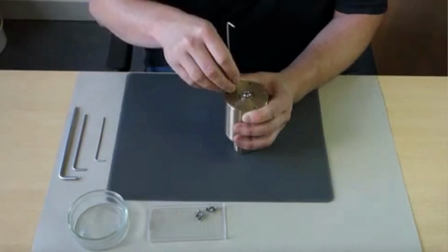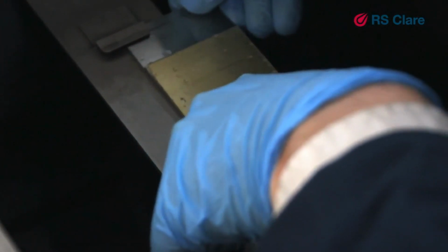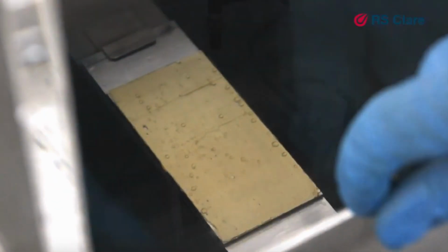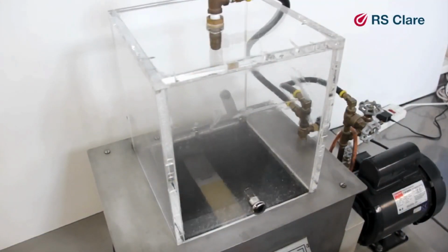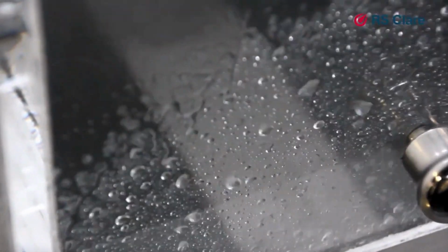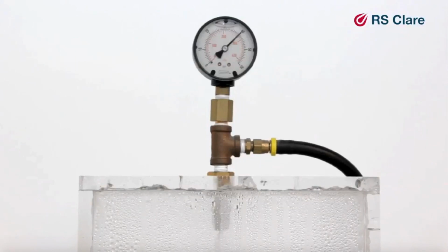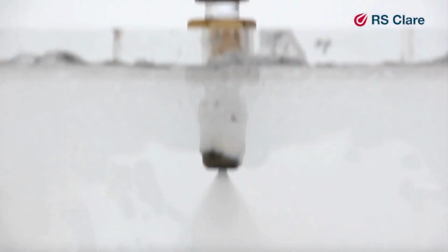The water spray-off, this is the one where you're spreading the thin panel into a device. See, that's the panel. It's already got the grease spread on it. It's been weighed. It goes into this unit, and now you're going to be spraying on it for an hour at a given pressure, given volume, given temperature, all that stuff's controlled for. And this is the more severe of the two tests.